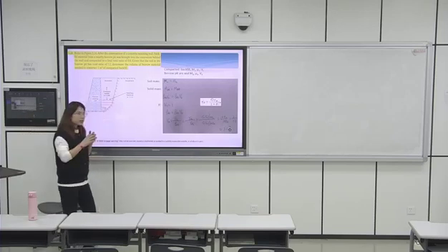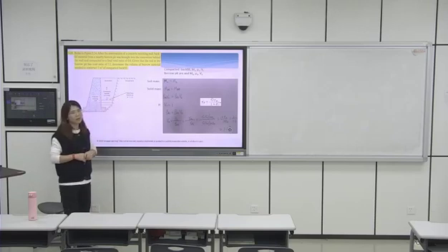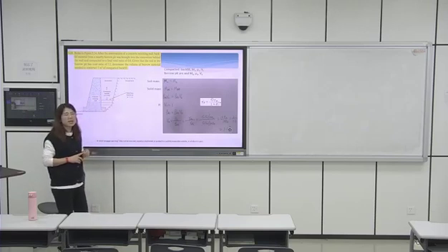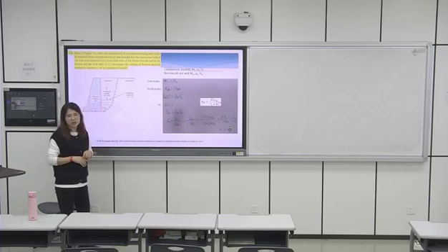And the clue to solve this problem actually is this. You need to find an equation between these two, between the soil from the borrow pit and the compacted backfill. What's the equation in here? The first thing you need to keep in mind is that the soil mass from here to here never changed, right?